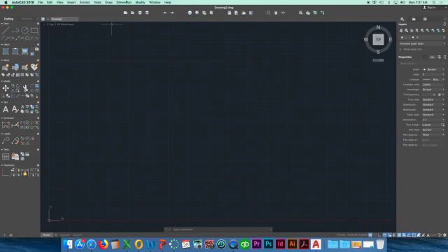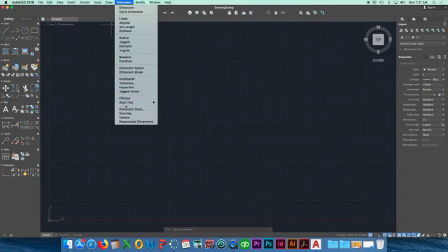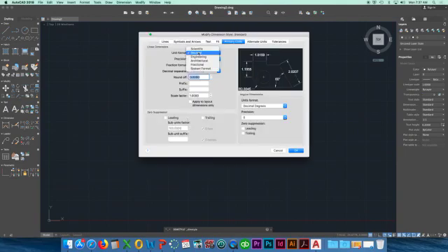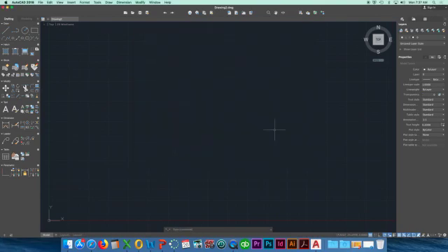Before you begin, as it says in the directions, under Setup, you need to go under Dimensions to Dimension Style. We need to modify, so under the cogwheel, modify. You want to change your unit format from decimal to fractions. Alright, now we can start our drawing.